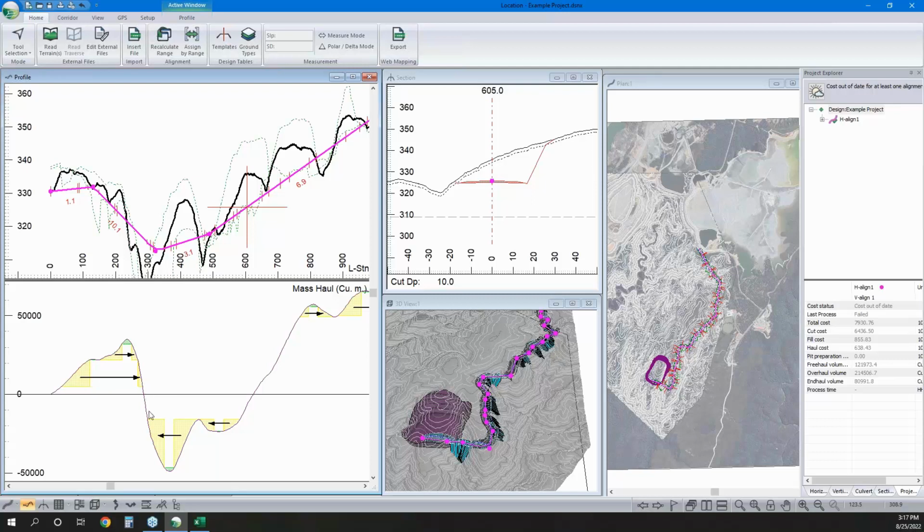Whereas once we go below the zero line, typical rule of thumb is then you're moving that material backwards. So we've created this deficit. We don't have material to address that deficit at the start of our road, so we're going to get past there and pull that material back. So that's the direction constraint.